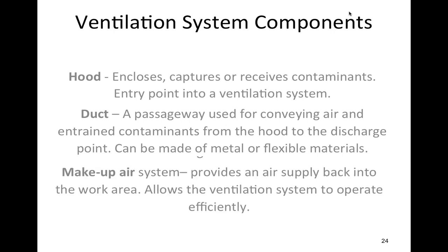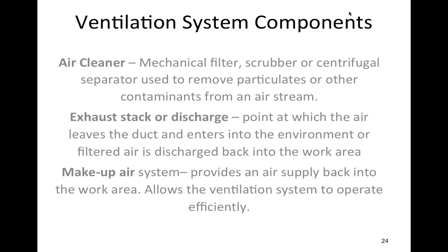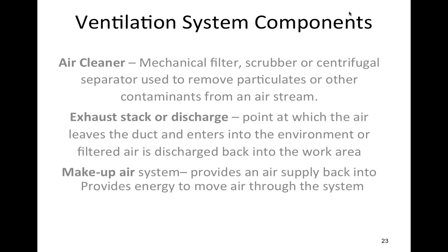Now, if you're sucking air out of the room and sending it outside, you can't create a vacuum in that room. This is not going to work unless you supply replacement air for that room. If you don't supply replacement air, you're not going to get the air moving as much as you want. Again, typical exhaust ventilation system.